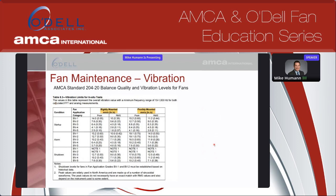So when we talk about the vibration levels, there's a couple points we want to make. This table's from AMCA 204, the vibration and balance quality standard. And a couple things is, typically when you see different mountings, you'll see a rigid mount where you're basically anchored to concrete or something like that. And then you see flexibly mounted where you're up on isolators such as spring or rubber in shear, or even a vibration pad.